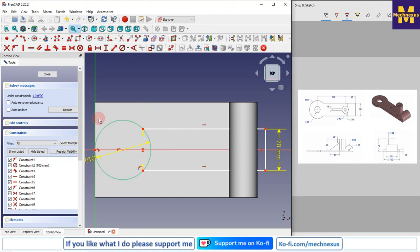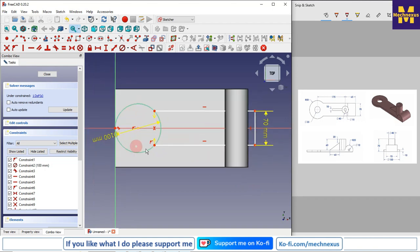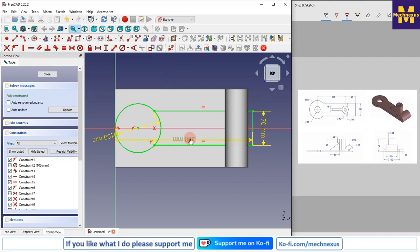So basically I want to remove material here at this portion. Now I will make it constrained, so I will select this point and this point, and I give some rough dimension, say 300. So this is fully constrained. Now I will select all my sketch and make it a construction.